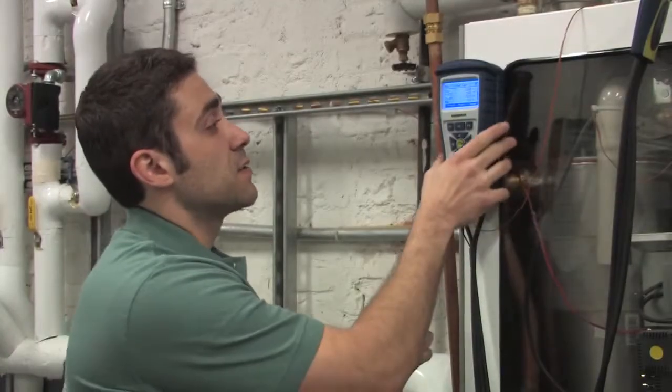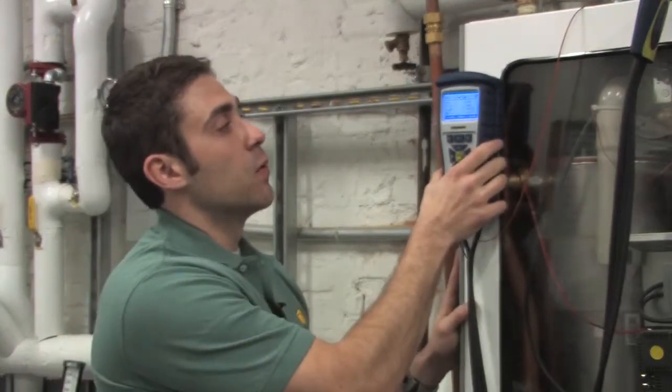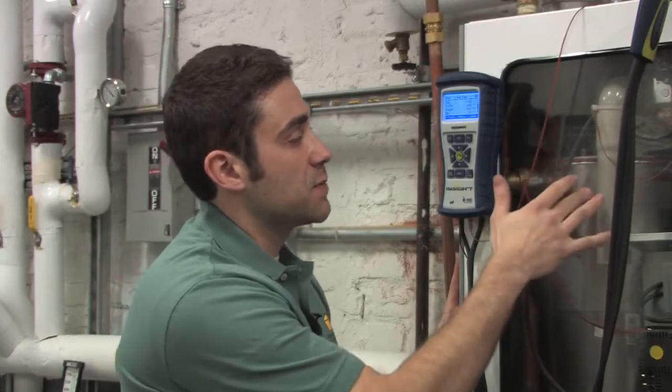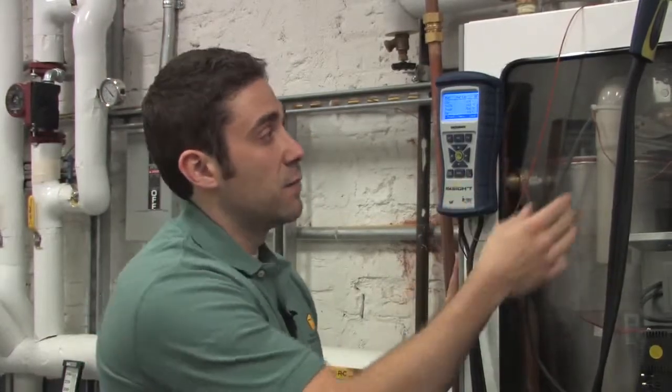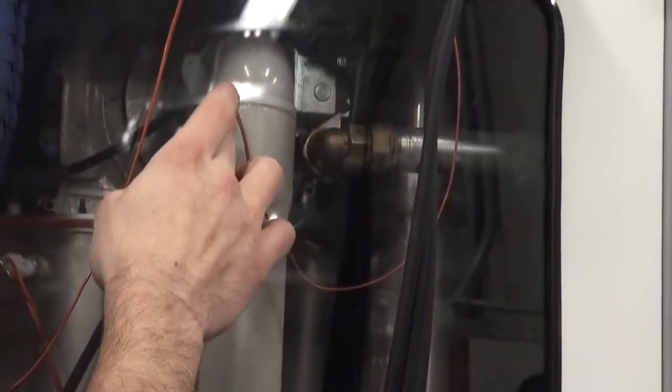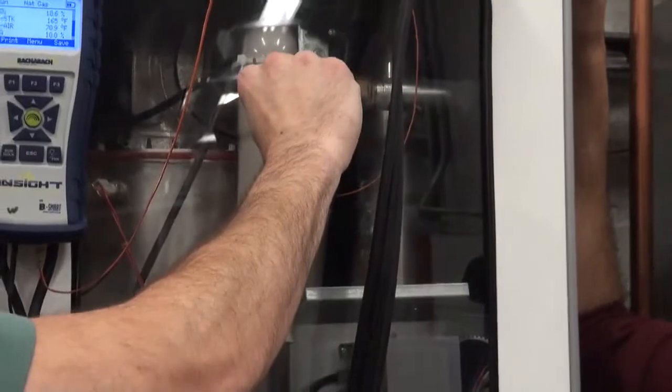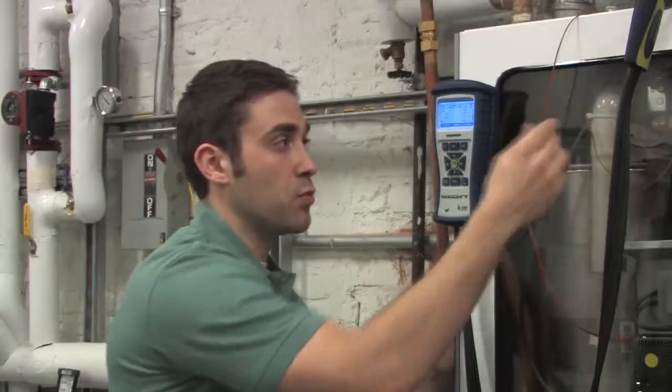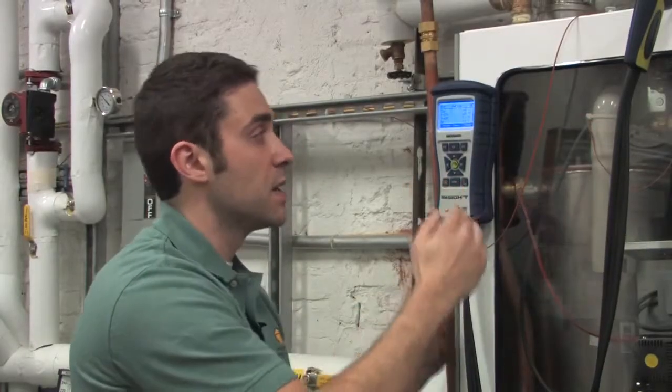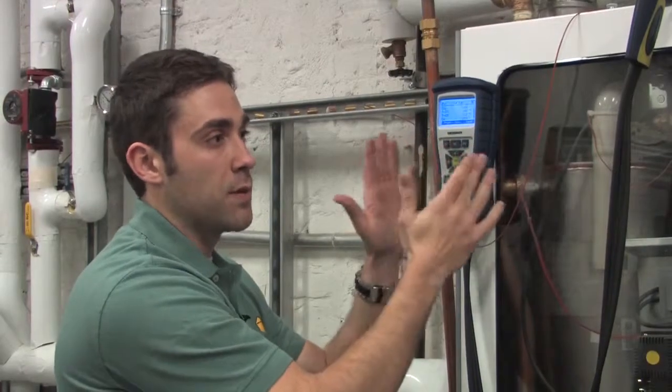The adjustments on these are at the gas valve on this one. So with this, we have the fan adjustment, which we can use to adjust the speed of the fan. And then we also have the amount of gas that can be pulled in. So right now the fan's running at a speed where it's pulling air in, and then it's also pulling gas. If we choked back a little bit on the gas and brought less natural gas in for the process, our numbers would match up to where we want them to be. We would bring less fuel into the air that we have available, and we'll get a much cleaner combustion.